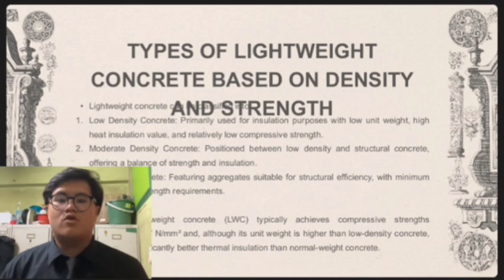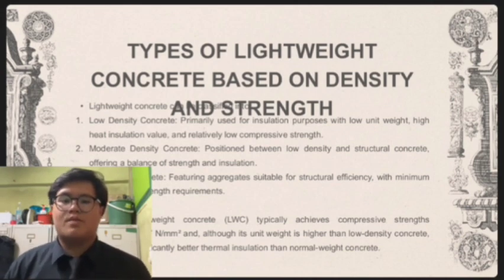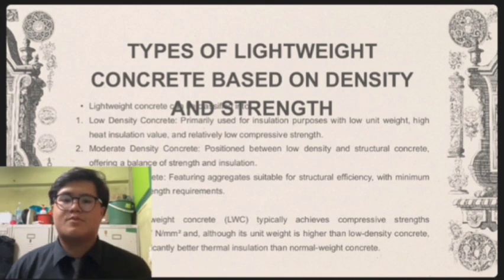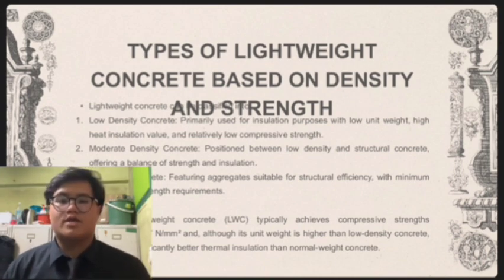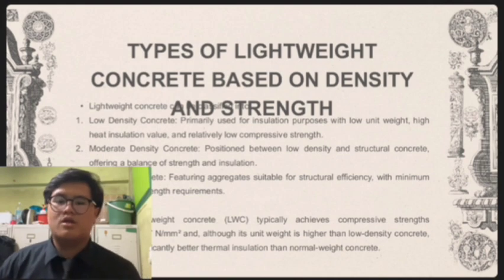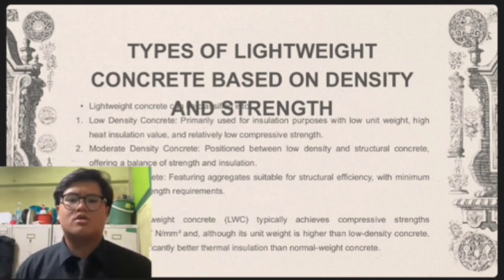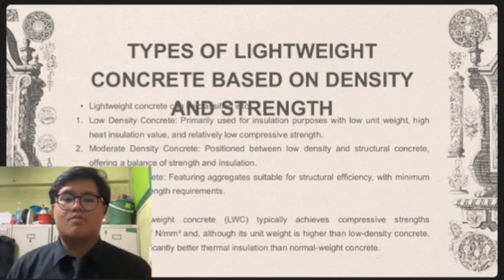First, we have low density concrete. Think of this primarily as an insulator because it has very low unit weight. It offers exceptionally high heat insulation values. However, the trade-off here is strength. It has a relatively low compressive strength, making it ideal for non-structural insulation purposes rather than load-bearing walls.